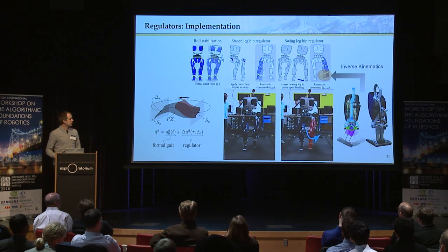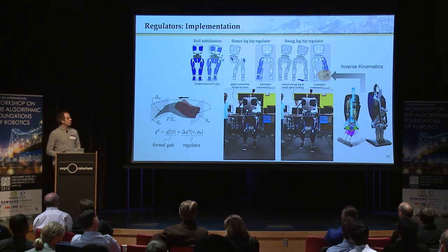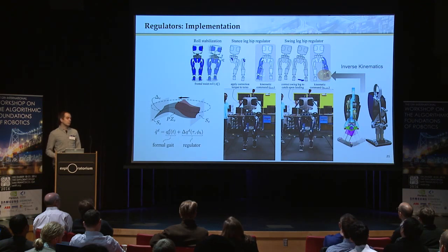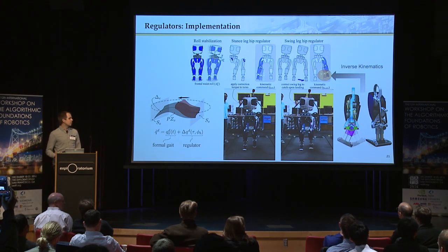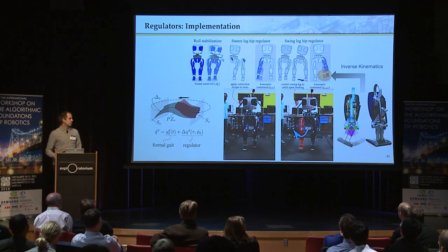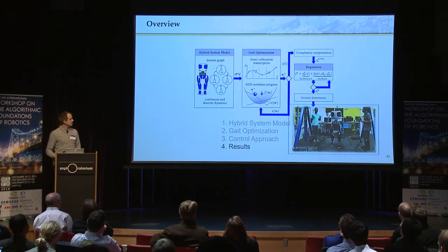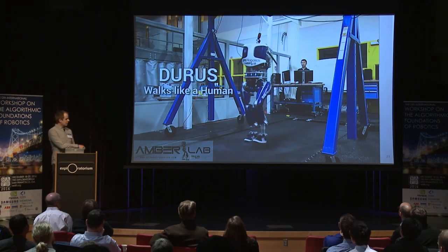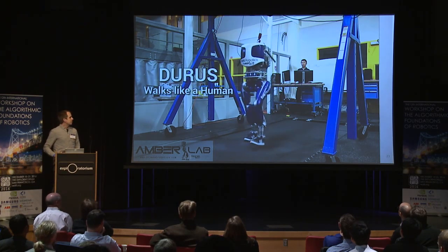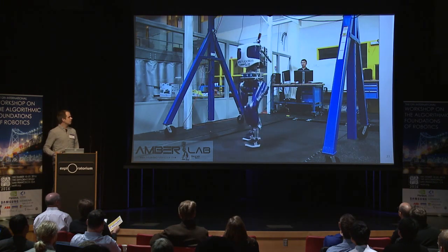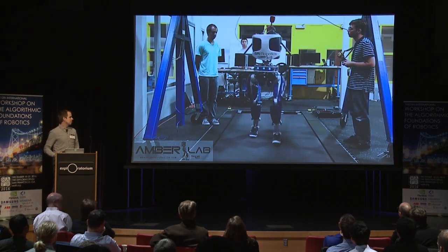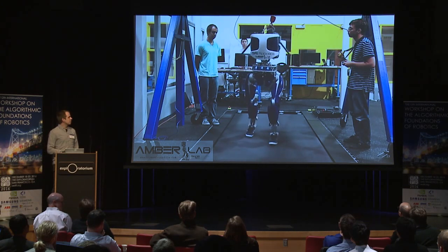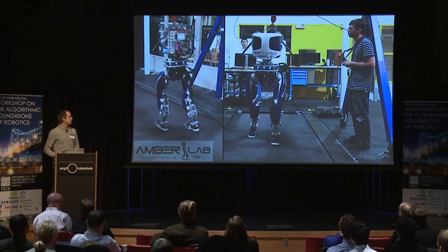And as we adjust that lateral foot placement, what we see is that one of our virtual constraints, specifically the swing ankle world orientation, was very important with keeping the heel parallel to the ground. So we run an inverse kinematic solver to zero that virtual constraint. So we have the resulting walking here, where we can see a lot of the heel-toe action being played back on the robot. This walking had a step length of just under 0.4 meters, and we can see that there is some oscillations that weren't present in the earlier video.